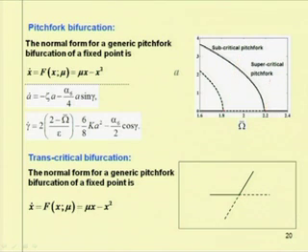So, this point is a supercritical Pitchfork bifurcation point, but for this point, initially we have one stable trivial state, but after this bifurcation point we have both unstable trivial and non-trivial responses. So, as both the trivial and non-trivial responses are unstable, from a stable branch we are getting an unstable branch, that is why this is a subcritical Pitchfork bifurcation point.